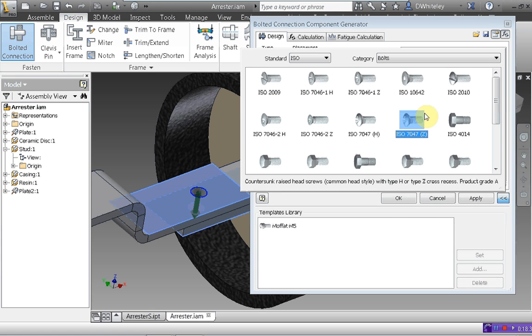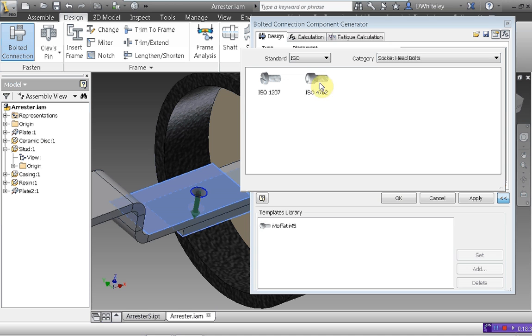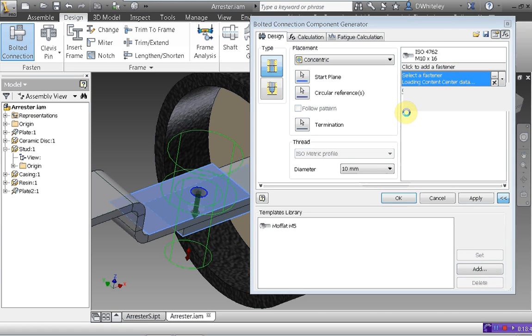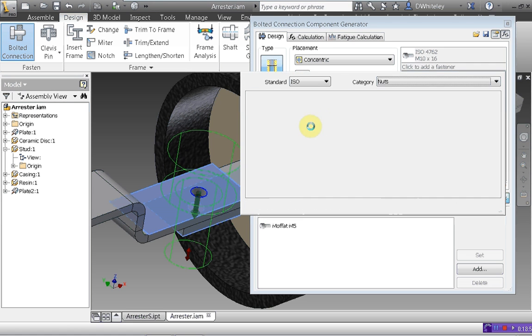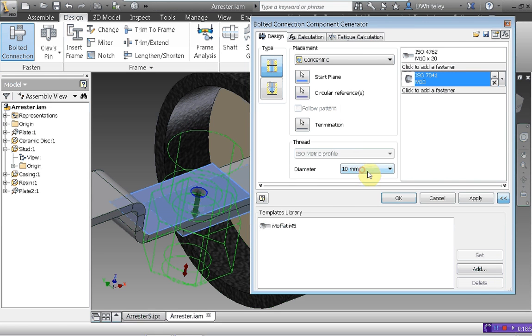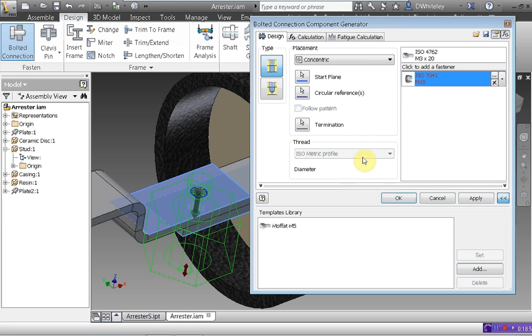So really the best way of working with this is to create your holes in the multi-body model, and threads as well, remembering to select the solids as you go, as I showed you earlier. And then when we come to add our fasteners, when we do a bolted connection, just remember to put the right size in here, you can't use by hole as a reference.